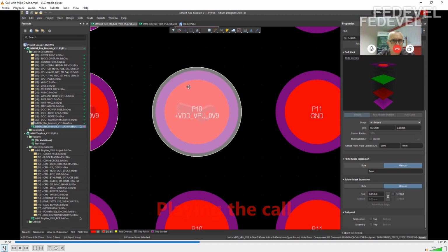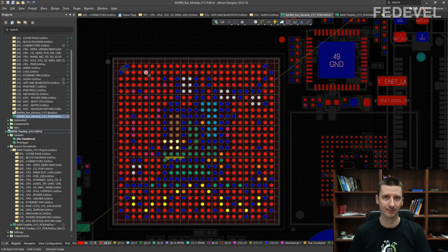Okay, but you drill all the holes at once, just how they are filled? No, if they're through vias, we have to just drill. So you have to drill twice then. Yeah. So in essence, what you end up doing is you end up having two drill programs. You end up having two lots of plating, and that's where the cost goes up slightly higher, and the lead time, manufacturing time, goes higher because you've got more processes to run. What we have just learned from the previous clip.